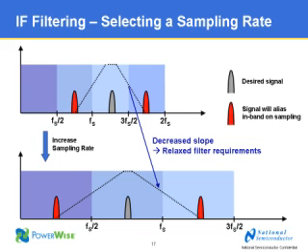So in this diagram, let's say that the signal we want is the gray signal. That's our desired signal. Unfortunately, that means that those two red signals in the other Nyquist zones, after the sampling operation, are going to sit on top of our desired signal. So that's bad. What we need to do is use a filter to attenuate the red signals. Let's assume we need some level of attenuation, and that's what's drawn on the top of the slide.